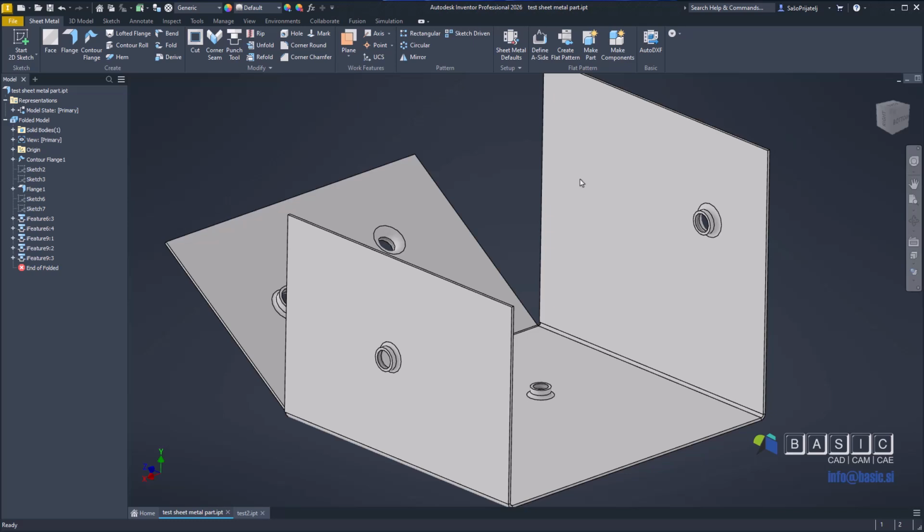Punch tool was created by modeling this shape in a bit specific way to avoid having too much additional geometry for setting position. And after the punch was created, we also changed the way how the dimensions are defined by opening the iFeature itself and setting the system of setting dimensions in the iFeature definition table.